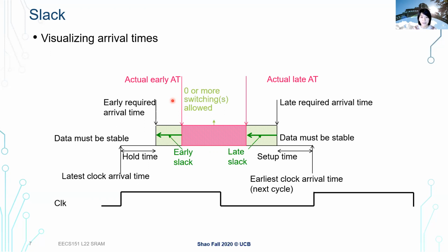So this is basically a very typical delay behavior or timing behavior that you will see in a lot of circuit analysis. So we always need to have enough buffer for both our setup time and hold time. And then between those, we have our time for our transitions. And typically there's also some slack we need to provision to make sure our circuit can behave correctly.